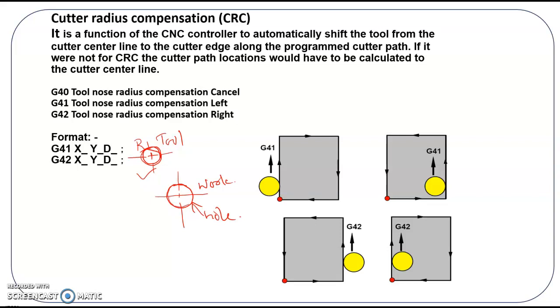Then the center line of the tool will be the assigned reference center, and this will be the center of the workpiece, otherwise the hole. When we call this tool to align with this hole location using a program, the center of the tool will exactly match the center of the hole.